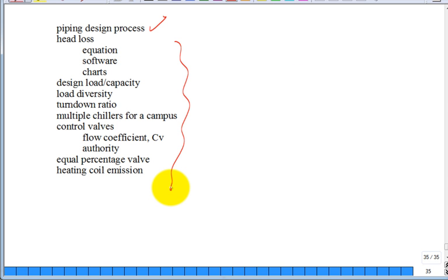They think, oh, I calculated a friction factor, it's 22. Is there a friction factor anywhere on that Moody diagram of 22? Well, I don't know what the friction factor should be. I said, what's the range of a typical friction factor? I mean, do you find a friction factor below 0.01? Oh, well, it could be 0.000. No, it can't. Go find me a friction factor. You know what I mean? So the range of the friction factor is not that tremendous.